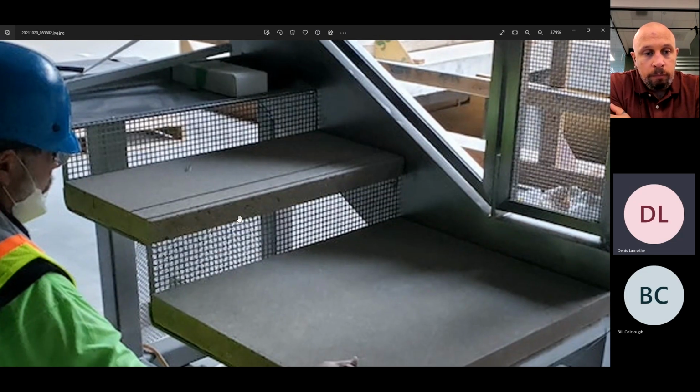Terrazzos will also generally come with a nosing strip. It's not just terrazzo, wood as well, but in this picture you see that nosing strip that's applied. That's to prevent any slipping beyond the nosing, so that people don't fall and hurt themselves. Nobody wants that. That could often be a stainless steel bar that's just inlaid in the terrazzo.